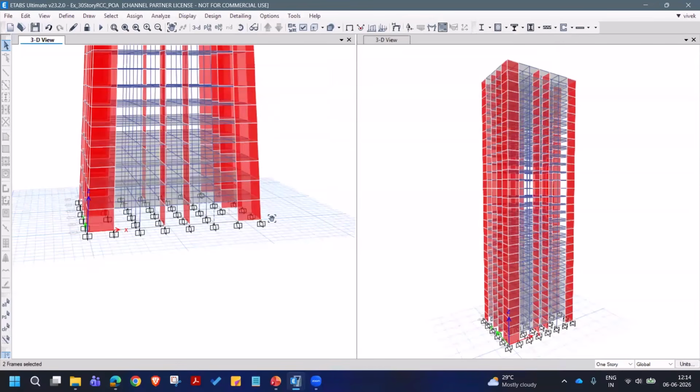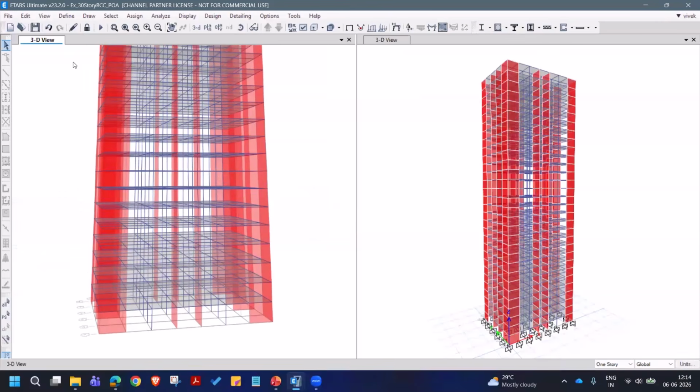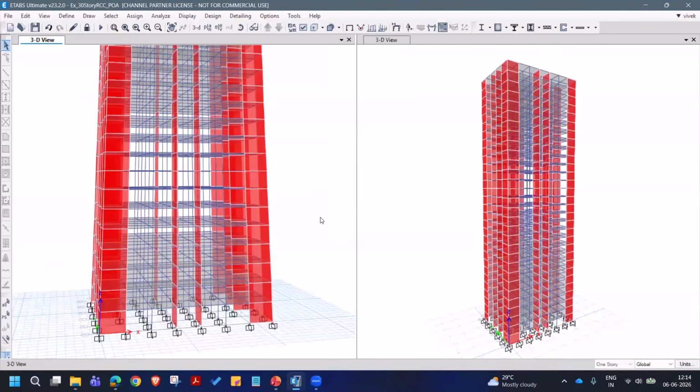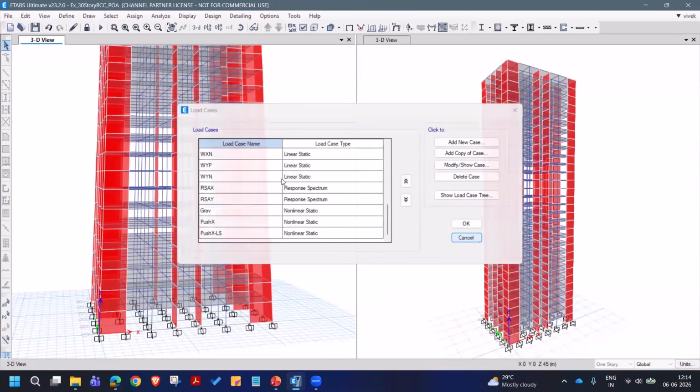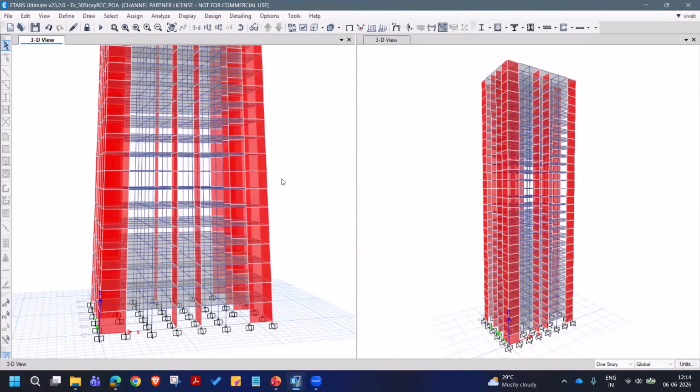All right. So we have performed the nonlinear cases, the pushover. So the basic idea is when the structure is pushed to the maximum allowed limit of 450 mm in the first case, and second case double of it, 900 mm.